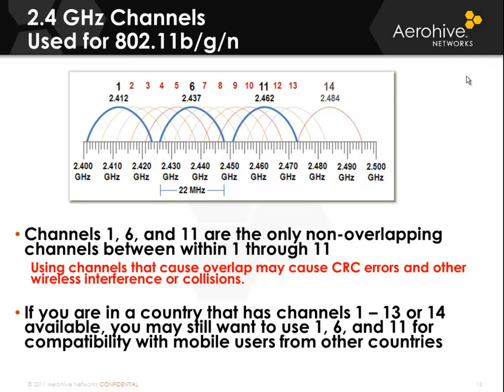That way, if you're using spread spectrum technologies and you're using a 22 megahertz wide channel, if you split it in the middle right off of 2412, you'll see that you go down 11 and up 11 from there, and it'll take you to 2.401 as you go down towards the bottom, keeping you within the legally allowed non-licensed frequency range. When you go up for the other 11, it'll take you to 2.423, which unfortunately is the center frequency for channel 3. So you'll see there is some overlap from channel 1 all the way up through channel 3 just with what channel 1's causing on its own.